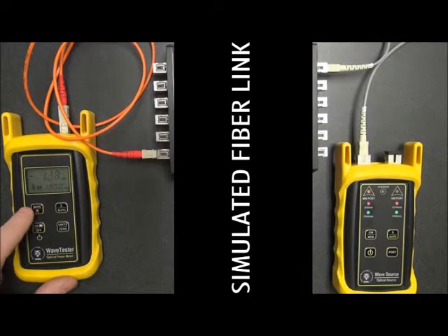And finally, we store a reading for port number 6. As you can see, every time we stored a reading, our fiber numbers incremented by 2 because we were storing a reading for 850 and 1300. So we've stored readings for all 6 fibers in the meter.